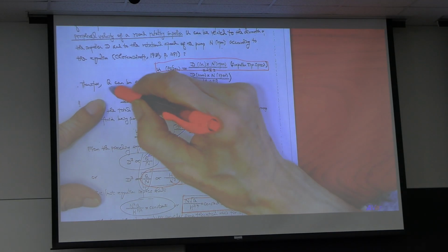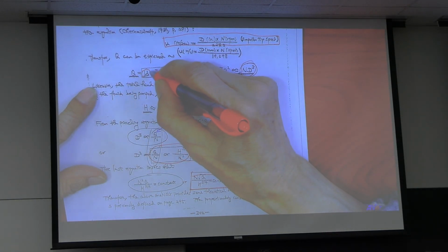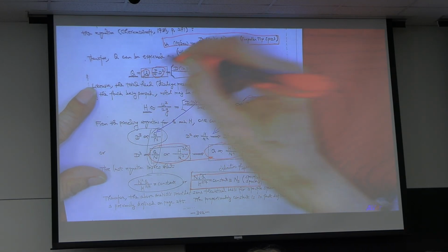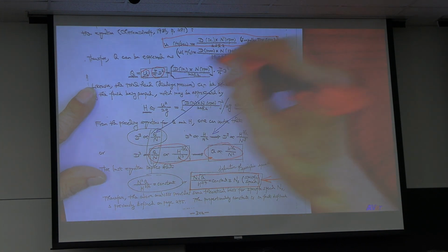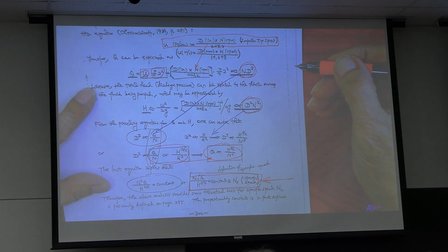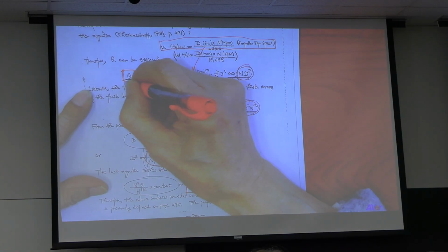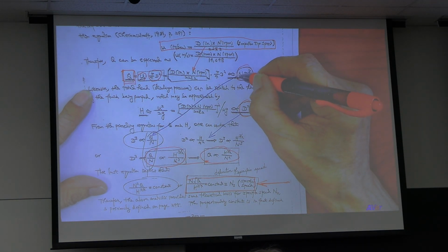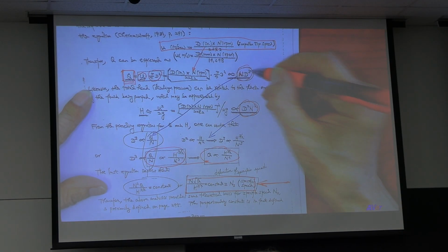So volumetric flow rate Q, this linear velocity, pi over 4 diameter square area. You plug in, this gives us pumping rate Q proportional to impeller speed N, diameter to the third power.